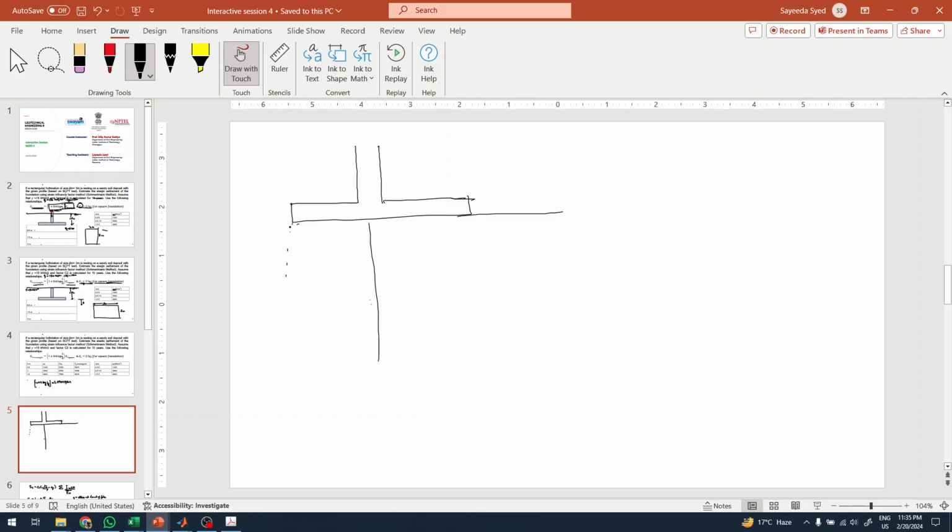You see, we used to draw those pressure bulbs, something like that. So there is this diagram of influence that Schmertmann has given, with Z. There is an influence factor value, and what we need to do is first identify the foundation, what type of foundation it is.